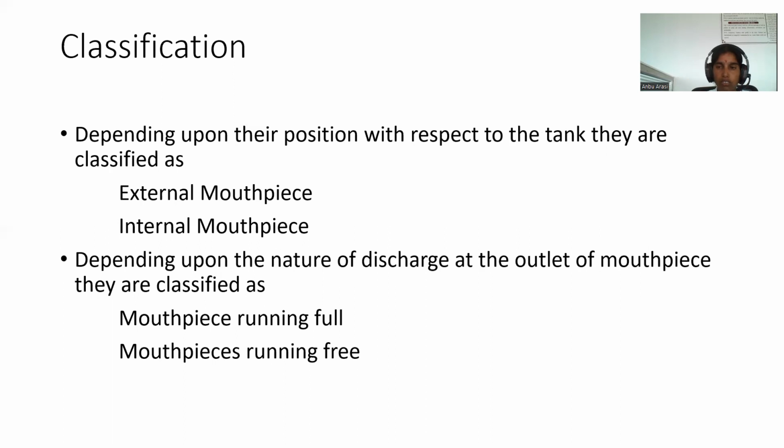This classification is only for internal mouthpieces, which are known as Borda's mouthpieces. A mouthpiece is said to be running free if the jet of liquid after contraction does not touch the sides of the mouthpiece. But if the jet after contraction expands and fills the whole mouthpiece, it is known as running full.